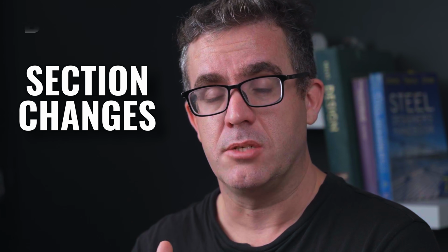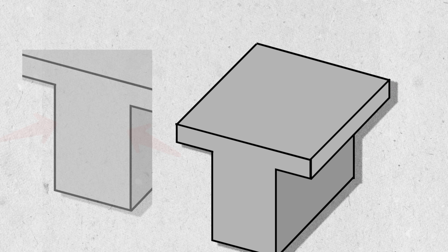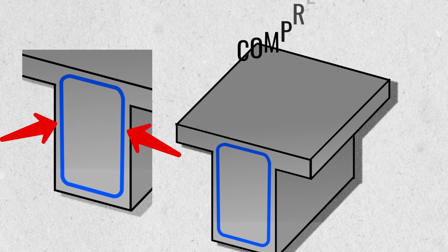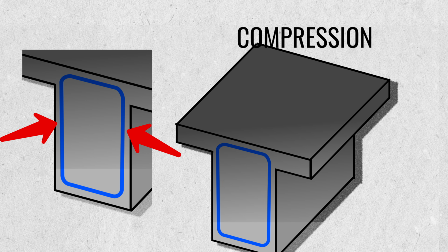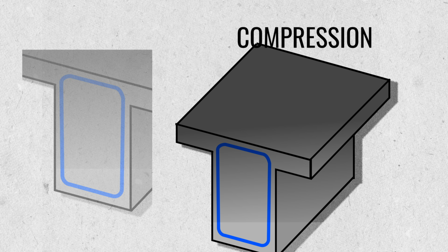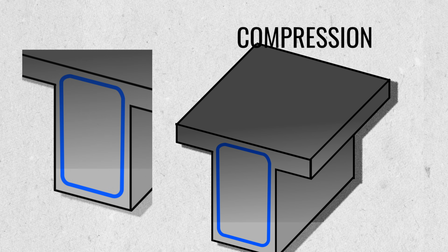Now, the one place that transverse shear is super critical is when the section changes based on its height. If you've got a T-section of a beam, you have to watch out for the plane just before the T-section occurs, as the top section will be in more compression. So there are more stresses that need to be applied through that interface. You need to check whether you have enough reinforcement through that joint to allow those transverse shear forces to occur. Now, that's just the transverse shear.